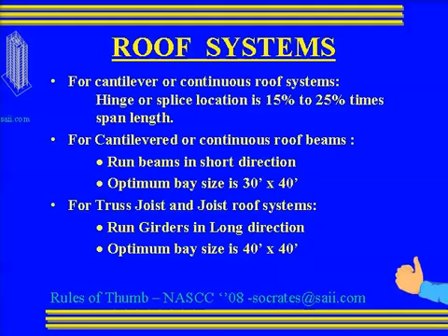And the advantage of the first system with the beams and joists is that you end up with essentially a uniform thickness system. The advantage of the truss girders, of course, is a total package, but you end up with the heavier members on the long. But because they are open web, it is not such a big problem, because even if you need to run services, you can run them through the webs.